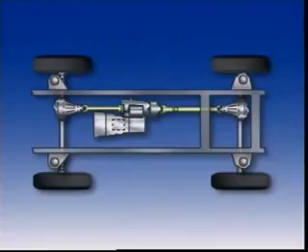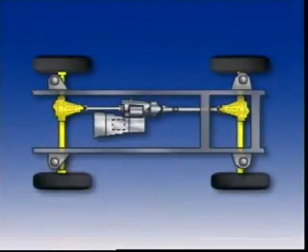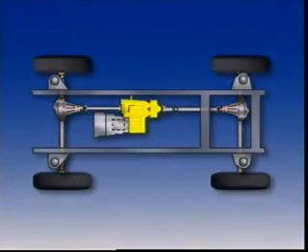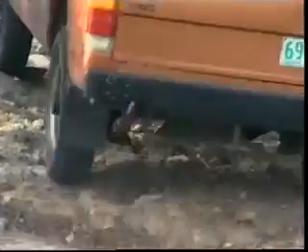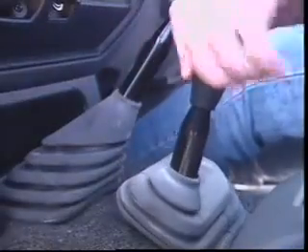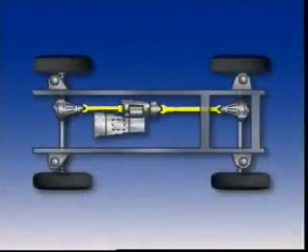A four-wheel drive vehicle has a propeller shaft, a final drive and differential gears, and axles for both the front and rear axle assemblies. A transfer case is attached to the transmission. Part-time four-wheel drive means the vehicle is usually in two-wheel drive and switches to four-wheel drive when needed by engaging the transfer case. It locks the propeller shafts together and directs torque through them to both axles.